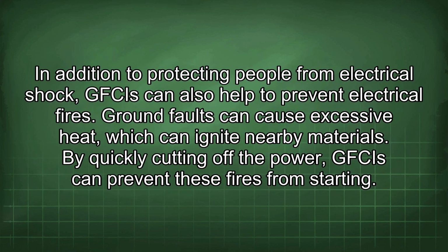In addition to protecting people from electrical shock, GFCIs can also help to prevent electrical fires. Ground faults can cause excessive heat, which can ignite nearby materials. By quickly cutting off the power, GFCIs can prevent these fires from starting.